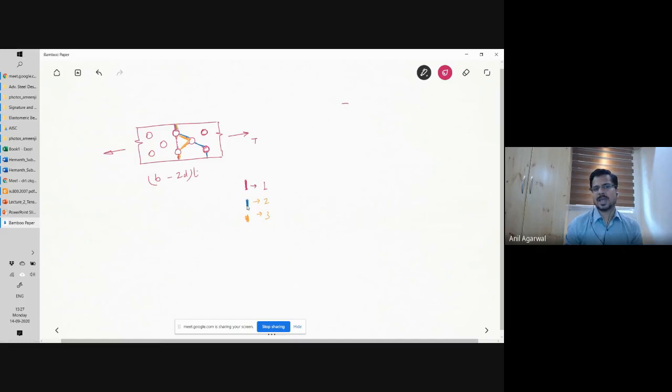Now, in these paths, your fracture path is not really passing exactly perpendicular to the load axis, right? So the stress state right before rupture is not pure tension. You are not exactly in the pure uniaxial tension domain.